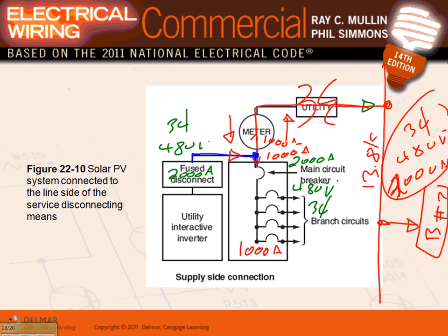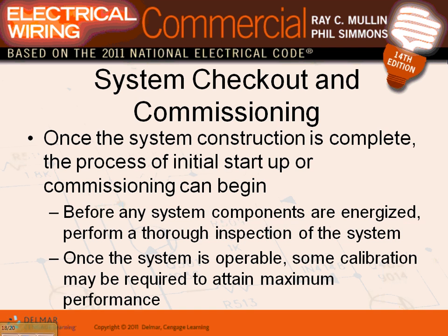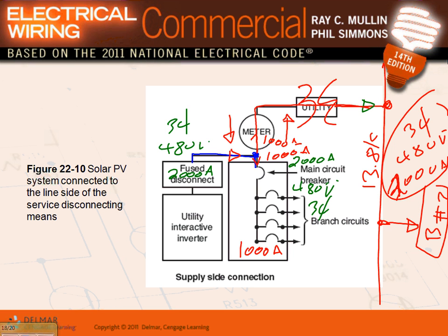Any questions? So can you see there's no limitation on the amount of power that I can generate here? No limitation on the amount of power. Okay, well look, you can't generate more than what your service entrance conductor can handle, otherwise you'll burn it. No limitation other than what your service entrance conductor can handle.